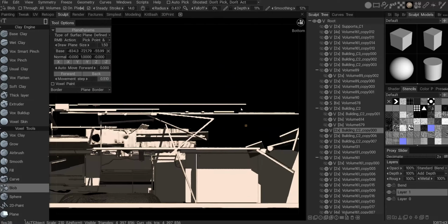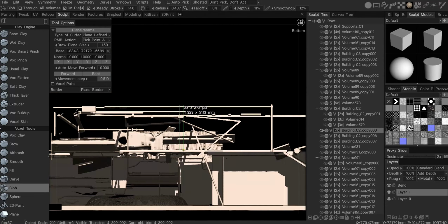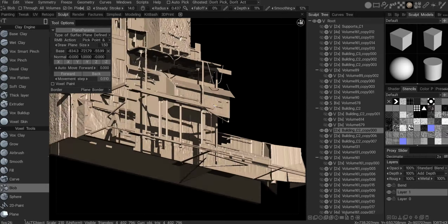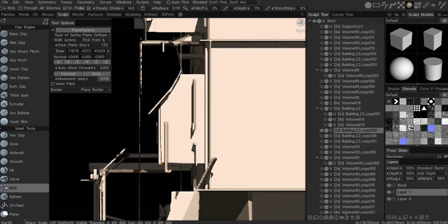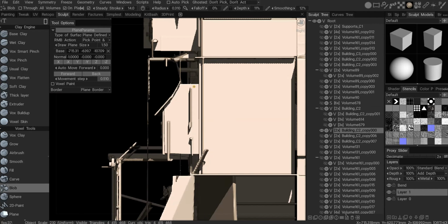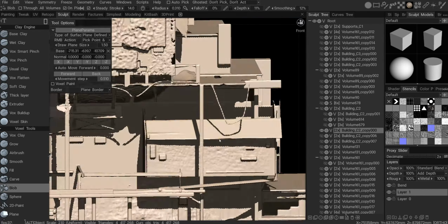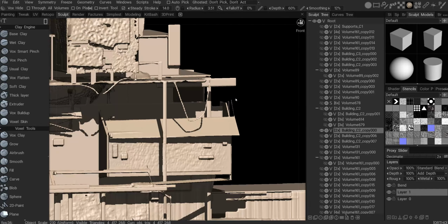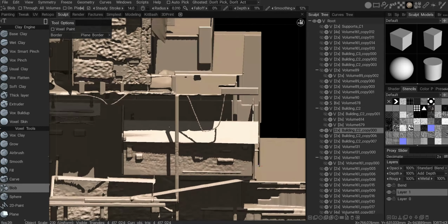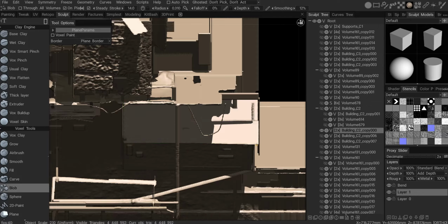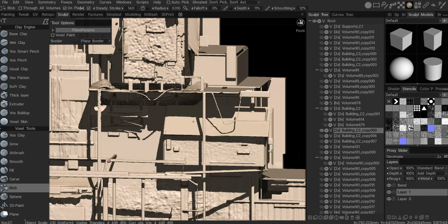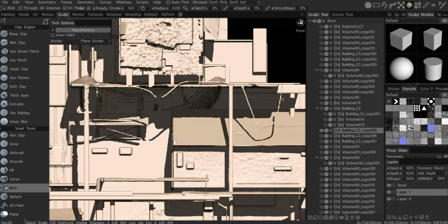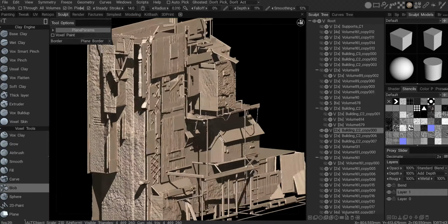And that's the problem with the blob tool. Sometimes if you put a plane on one side and start to create a blob from a different side, it can create like a 10 million triangle mesh or bigger. I talked to the developers about that issue and they were improving on it. I think in the latest version of 3D-Coat, 3D-Coat 2023, maybe version 20, subversion 20, they improved on it so it's much harder to kill 3D-Coat by creating a random huge mesh.